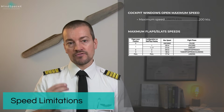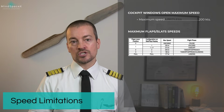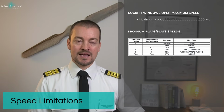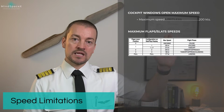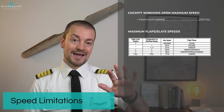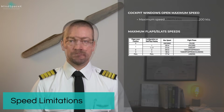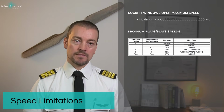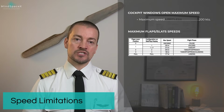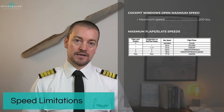Maximum speeds for flaps and slats are also structural limitations, but now placed on the flaps and slat panels. These speeds right here are for the pilots to memorize and know, but they are also placarded inside the cockpit on the instrument panel. The maximum speed in clean configuration is VMO and MMO. We're going to cover that in the next slide.